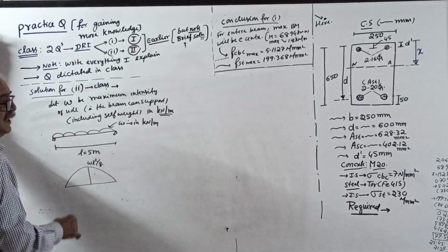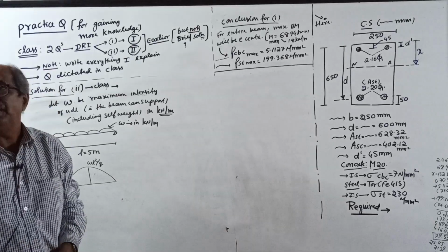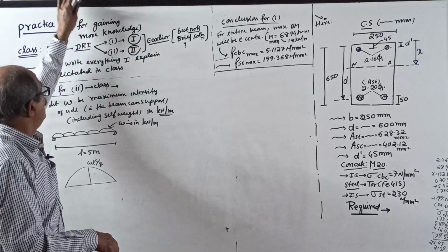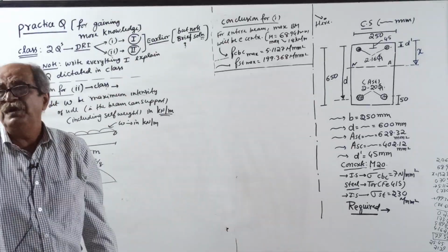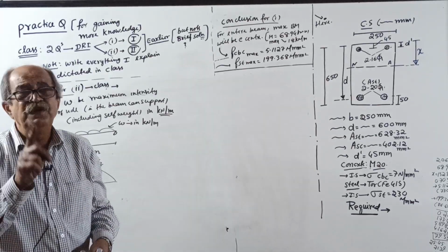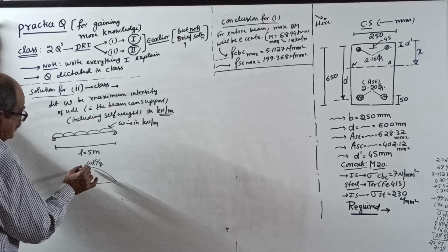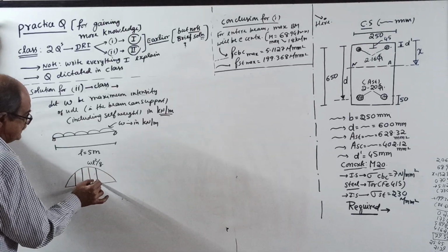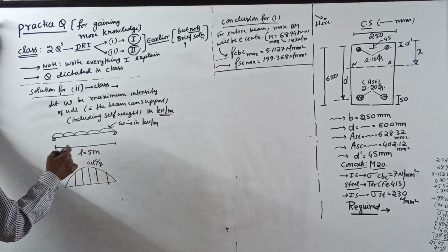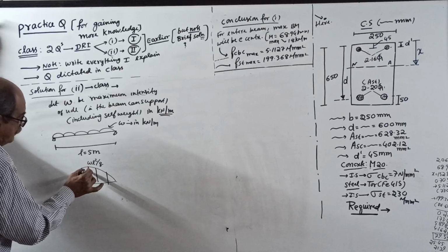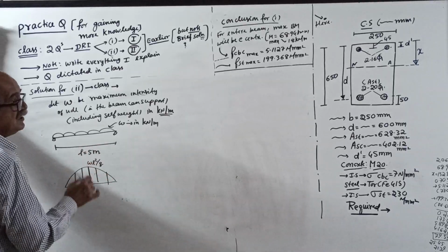See, different sections will have different bending moment. Now, they want to find the maximum UDL beam can support, means the beam should be safe everywhere. For this BM also it should be safe. So, when different sections have different bending moment, beam will be safe if it is safe for the maximum BM. This all you are right.